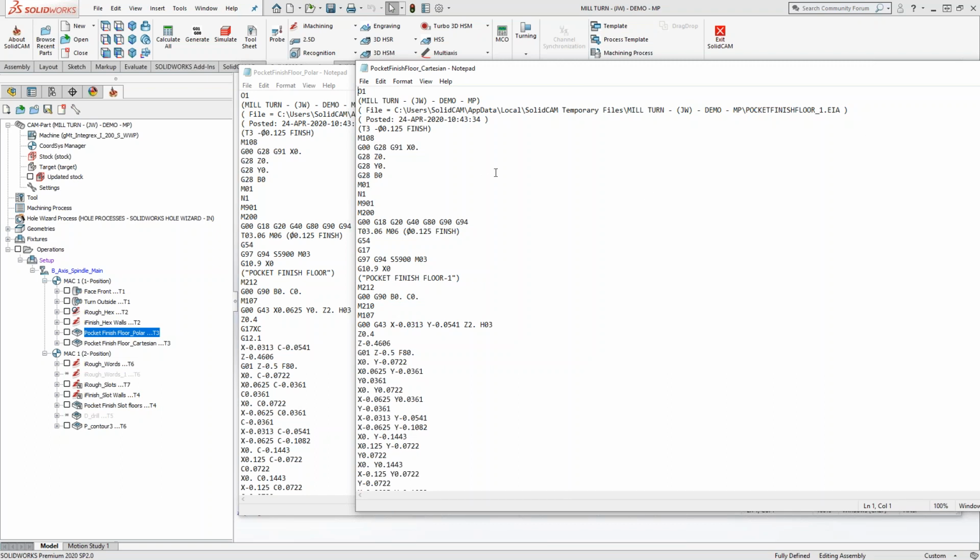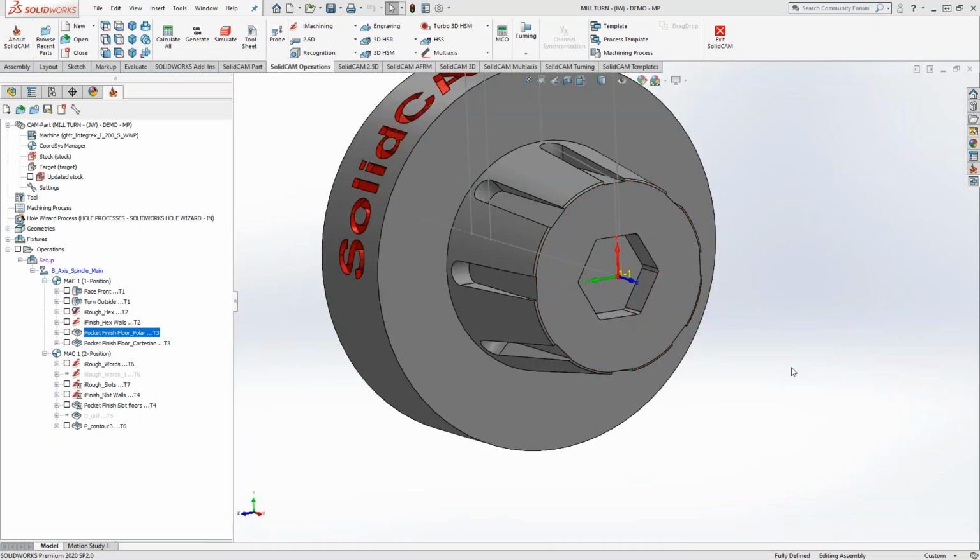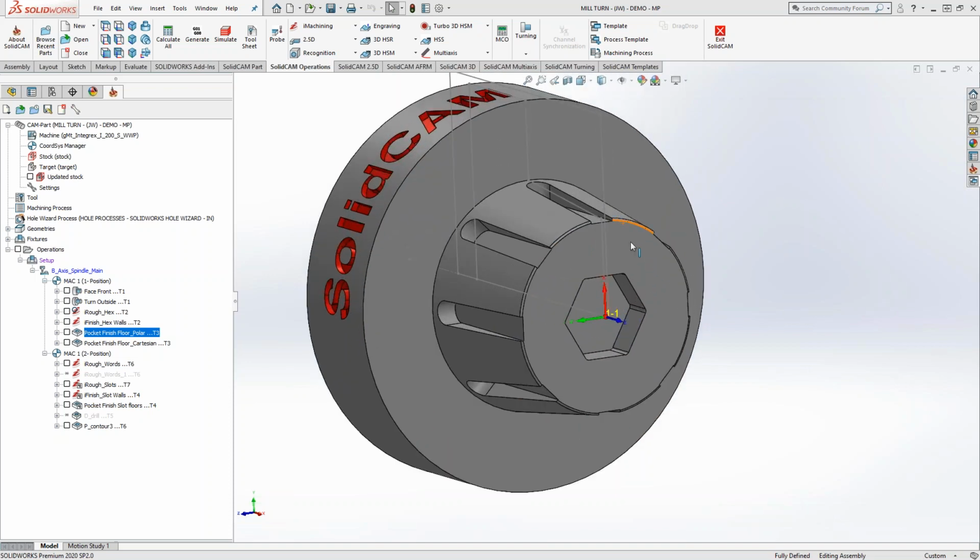Yeah, so this is where, oh, sorry, go ahead. Well, I was going to say this is where it comes in handy if you don't have much range on your Y axes for your mill turn. Exactly, because you'll notice that there was no Y code in that G code we were looking at, because it's eliminated the Y. The Y doesn't exist in that coordinate system. Now you can, if you need to, generate it as, instead of an XC plane, let me open that up.